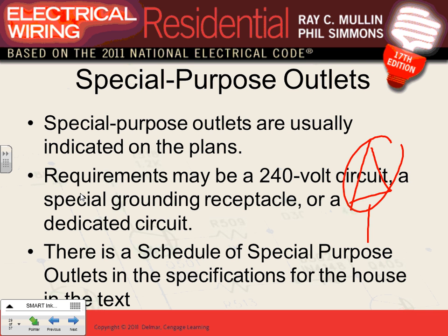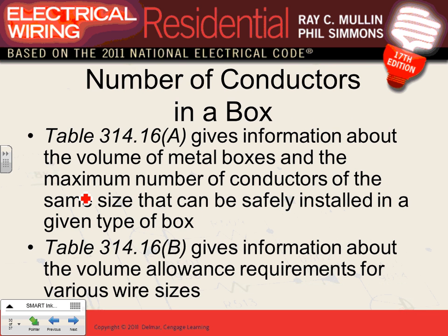What I would like you to do, Jeremy, my friend, when it comes to the range, is don't use the symbol for the duplex receptacle. It is a special receptacle. Then you specify the voltage and the amp right onto it.